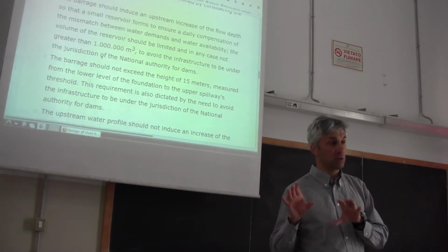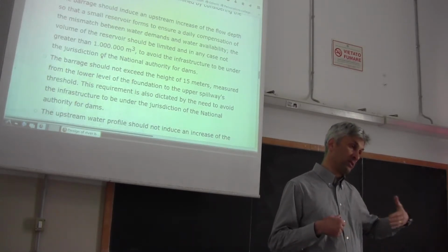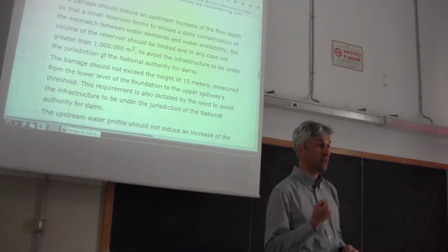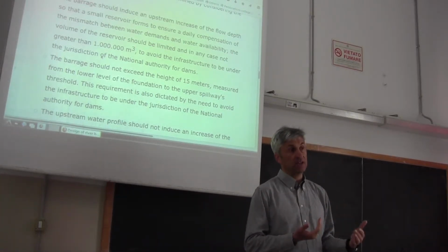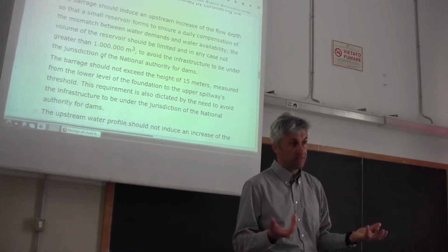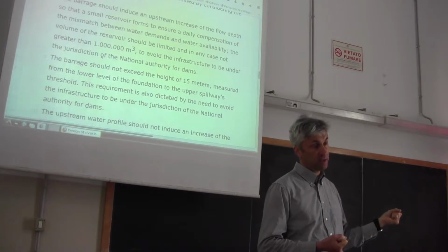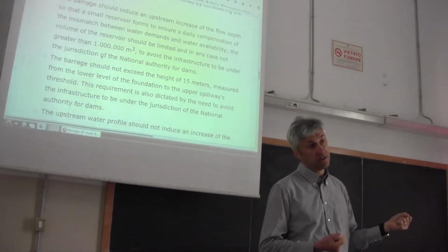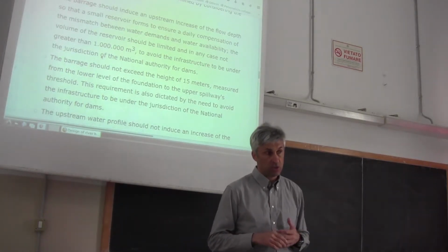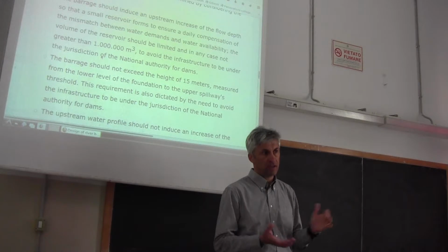If you don't have this control by snowmelt or ice melt, then during the day usually the flow in rivers is not highly varying. The water demand is instead highly varying. So during the day you have more demand of water in certain hours, and during the night you don't have any demand usually, or very low demand. So during the day, indeed, you may experience some hours where the demand is higher than availability, and hours where availability is higher than demand. So you have to compensate this. And we make a computation of the volume that is necessary to reach compensation, and how to estimate this volume is not part of this course, but the literature proposes several easy techniques.